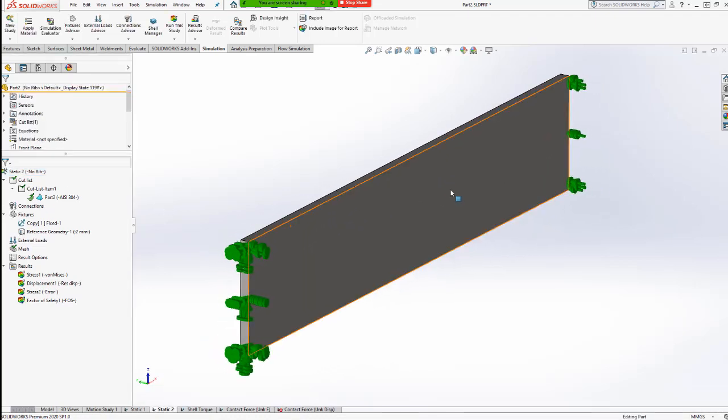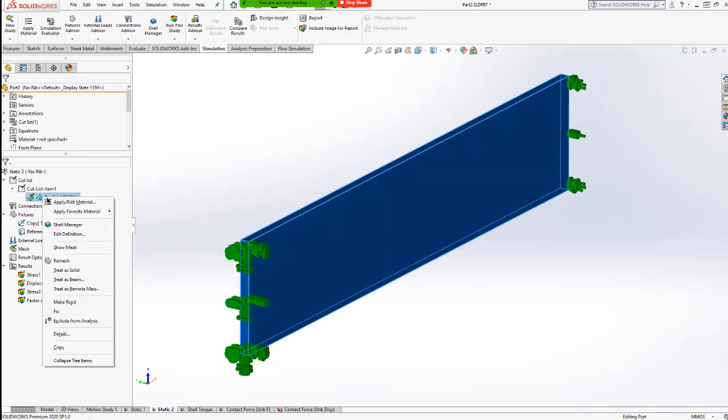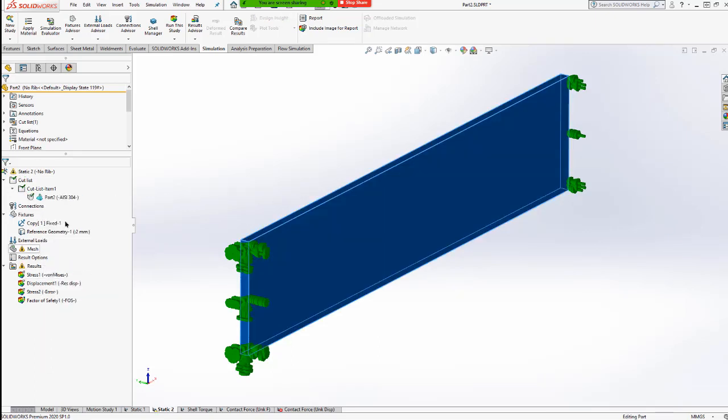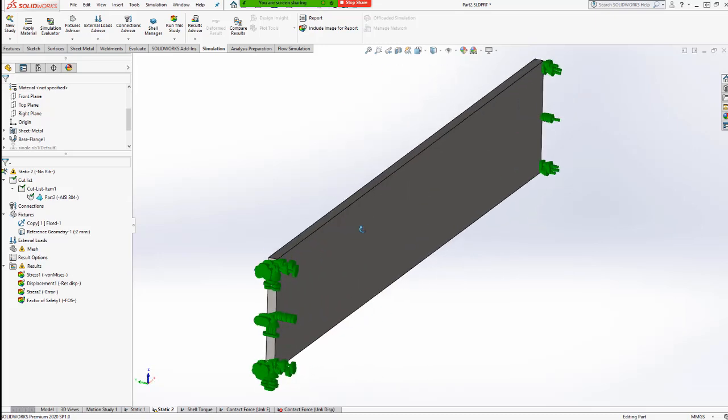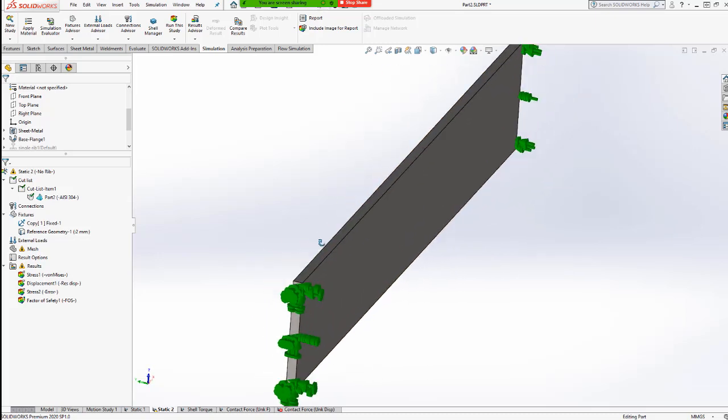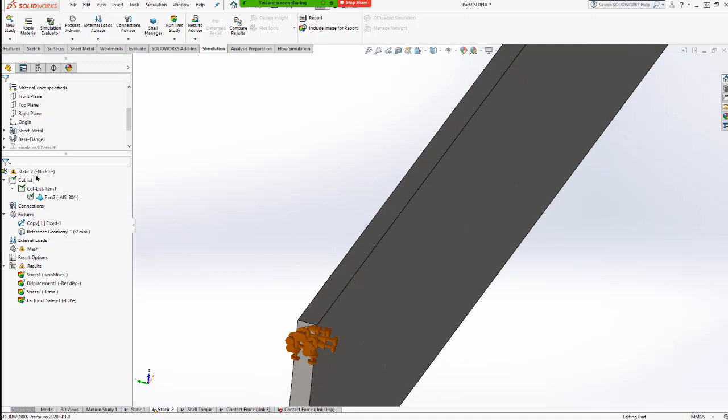And for all you sheet metal guys out there, if you were looking at the icons here, yes, this is assumed to be a sheet metal. And if we wanted to treat this as a solid, luckily, we can just, boom, throw that there. And now we don't have to run with the assumption of these two faces. And we're also choosing to trust the mesh refinement here. I'm going to quickly give that a run and show you guys the mesh right there.